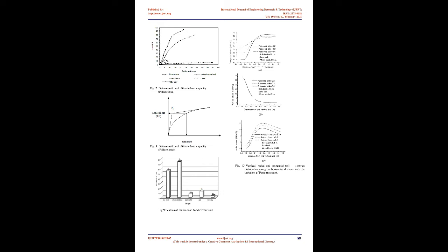A compression testing computer was used to statically load. At a constant load rate of 0.5 kN/min, all tests were completed. The deformations were measured with a 25 mm dial gauge and 0.01 mm accuracy and were also automatically measured with the measuring system. Results and analysis.